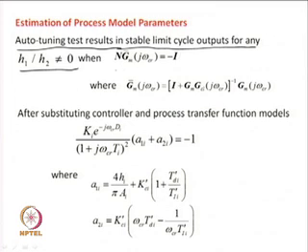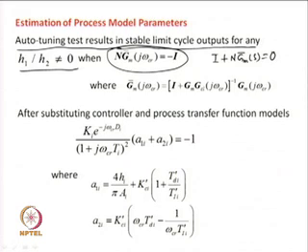Then, from the loop equation, the loop dynamics gives us the characteristic equation of the form identity matrix I plus GM bar S is equal to 0, and that in frequency domain can ultimately be expressed in the form of n times GM bar j omega CR is equal to minus I, where omega CR is the loop frequency.